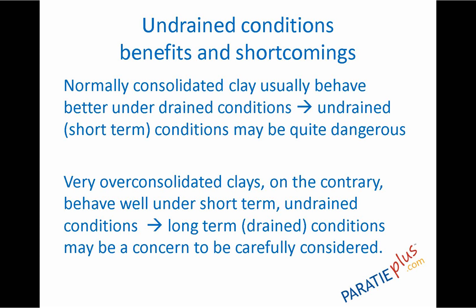On the contrary, very highly over-consolidated clays that in the past have been severely loaded behave better just after the application of loading. So undrained conditions are beneficial, and in that case, on the contrary, long-term conditions, where this effect vanishes, may be a concern to be carefully considered in design.